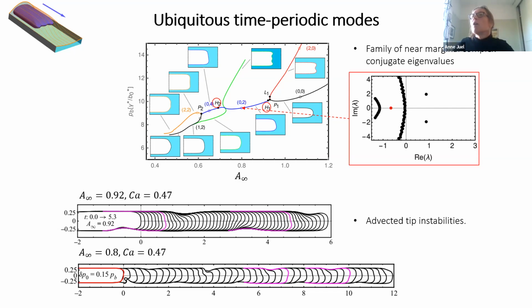So you calculate a certain number of most dangerous eigenvalues. So these are just like as many equations as you have nodes in your finite element mesh. That's right. So you get that exactly. So it's a discretized system that ends up having a very large number of degrees of freedom based on the mesh, and then you get basically an eigenvalue associated with each point. Yeah. And this is how you can characterize them as being weakly unstable. That's right. They look almost stable, but not quite, in terms of these numerical results.